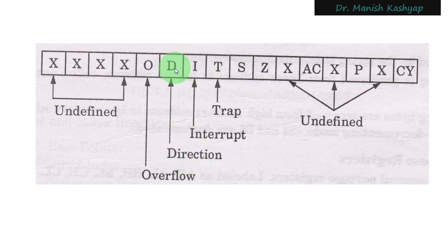In the 8086 instruction set, there are certain instructions which deal with string operations. By string operations, we mean, like in the C programming language, you must have printed hello world onto the screen or taken a string from the user as input. For those string instructions, if the string is kept in externally interfaced memory of 8086, do you have to read the string in forward order, that means in increasing order of addresses, or in reverse order, that is in decreasing order of addresses? Whichever direction you keep your string in can be set by this direction flag.